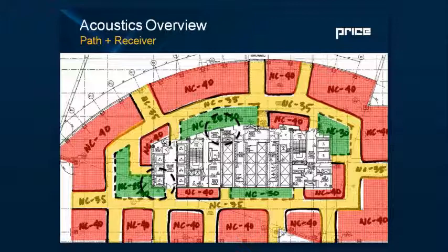I worked on a job where they had the option of either building a conference room along the facade or adjacent to the elevator shaft. And they chose the elevator shaft because they thought that the sirens from Times Square would be more problematic to handle. But unfortunately, that's higher frequency noise, so it actually would have been easier had they gone that route. So instead, they went next to the elevator shaft, and try as they might, we were never able to fully eliminate that noise. So it's just important, again, to consider where your spaces are and what they're next to.